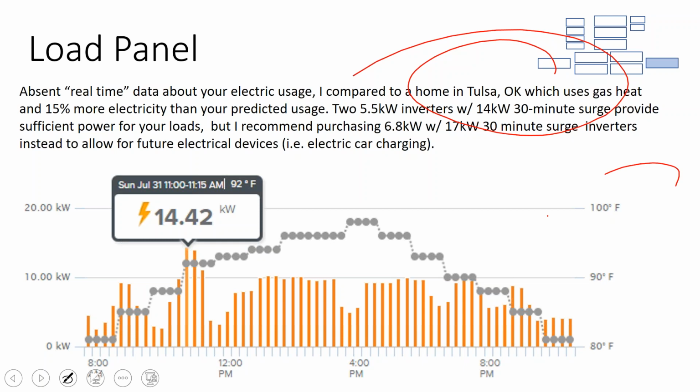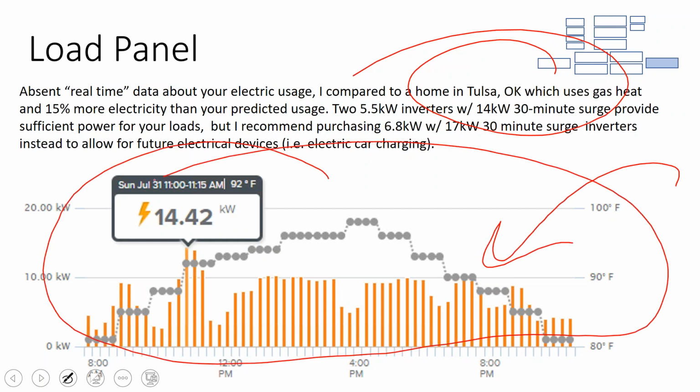But what I could get from AEP Oklahoma is that, without having to buy anything additional, they provide load profile data to their clients through the electric account portal on their website. So it may be worthwhile logging in to your utility account or your client's utility account to get this kind of data. In fact, there's a service called Utility API that for a fee will do all of that for you. You just put in the electric account info and it'll extract this load profile data if the utility is set up to provide it. That's supposed to be an advantage of the smart grid. I have a digital meter on my house and I don't have this data, but you might surprise yourself.